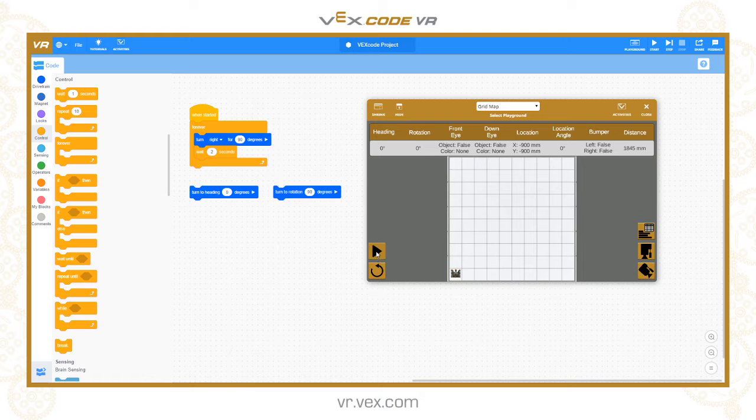So if I run this program now, and we do our first 90 degrees, heading goes to 90, rotation goes to 90. The next one, heading 180, rotation 180, 270, 270, so we're tracking at the moment. Back to 0, 360 for rotation, back to 90 for heading because we're compass east, and you can see rotation is cumulative, it's just adding and adding and adding, and so each time I do one full rotation of the robot, I'm adding an additional 360 degrees to the rotation value. So rotation is different to heading in that heading resets at 0 every time you go past the north point, and rotation is cumulative, and that works both positive and negative.